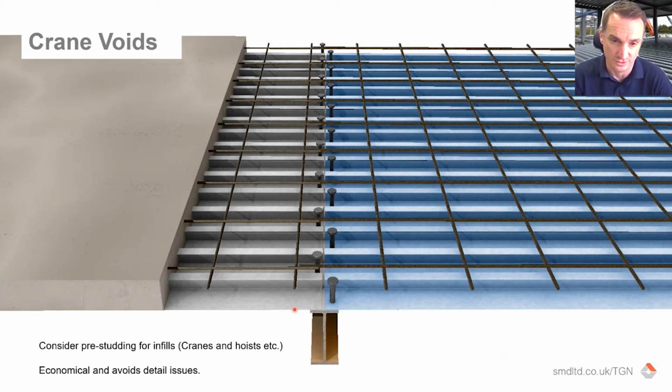Another option in that scenario, purely because that might mean a very small amount of welding of shear studs on a visit to site, which can be costly because you have to mobilize the rig and everything, the stud welding rig. The other option there would be to use a different type of shear connector on those beams, or not design those beams local to the crane as composite.